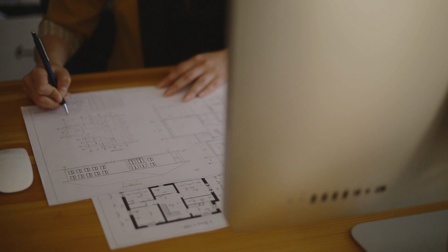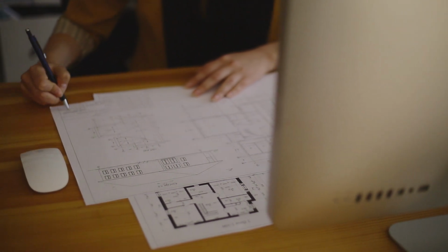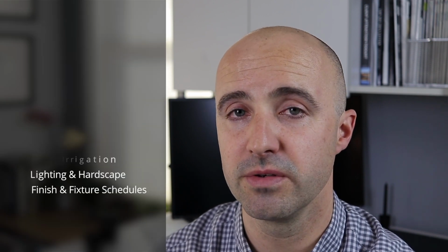You'll bring your plans into further focus in the construction document phase. The plans produced here will have a full set of notes and dimensions associated with them, and the plans you might expect to see would include your site plan, floor plans, building elevations and sections, construction details, reflected ceiling plans, the detailed plans from your engineering consultants, detailed planting and irrigation layouts, landscape lighting, hardscape plans. You'll also nail down your final materials and fixture schedules. At the end of the CD phase, your plans will be ready for permits, for shop drawings, and for contractor bids.